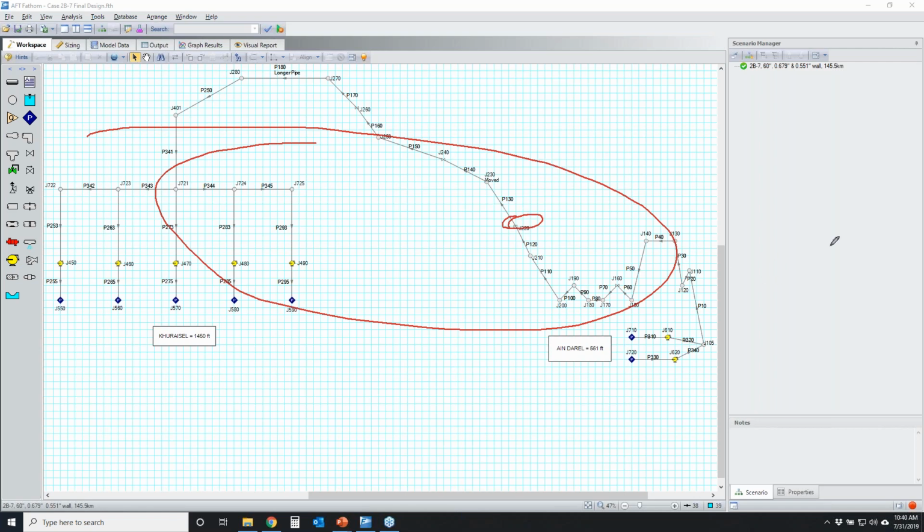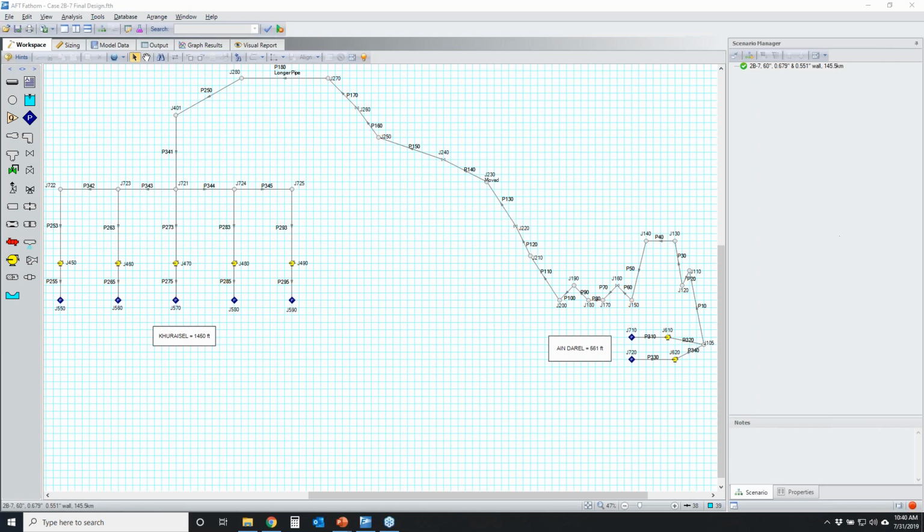Once I have changed the input, I put my flow and pressure requirements on my pumps, and I start running the system and tweaking values in order to get the system to work. I want to get the system to a convergible level, and that would be my starting case.